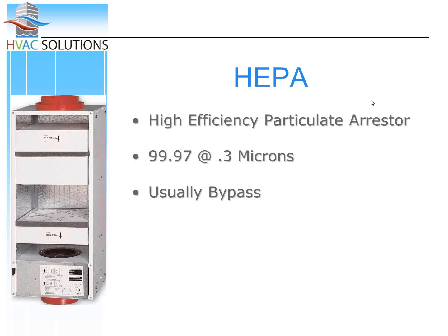I'd be very careful with the claims here. And if you sell a lot of these, I apologize. I would just look at the tests and look at what they're claiming and see which way you go. We do know that they are pretty efficient, because if you don't change these in about 3 months, you'll be out there on a service call. That furnace is going to go off on limit. So just be careful with that one.